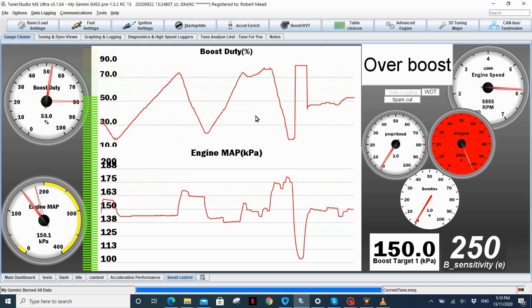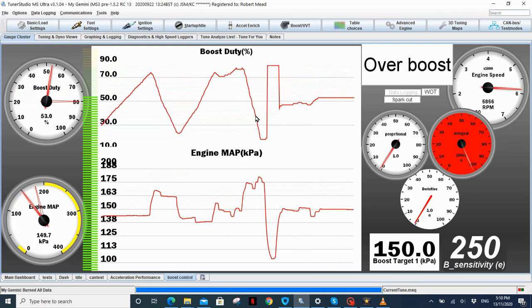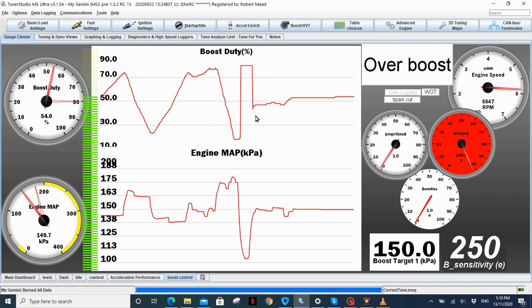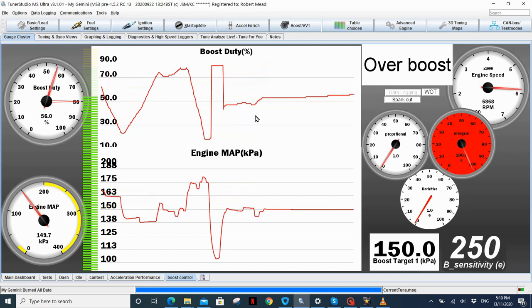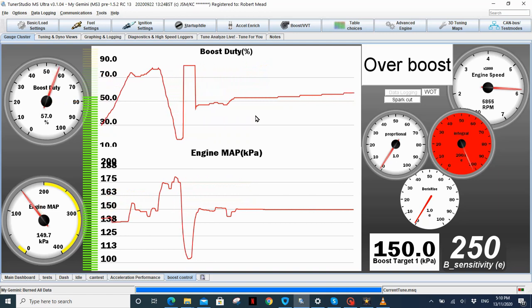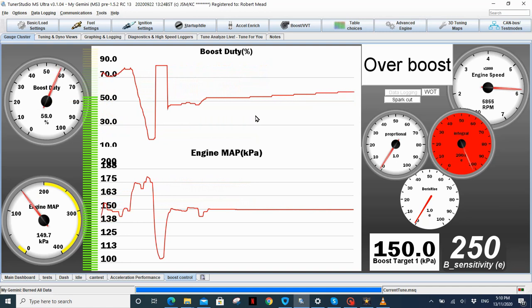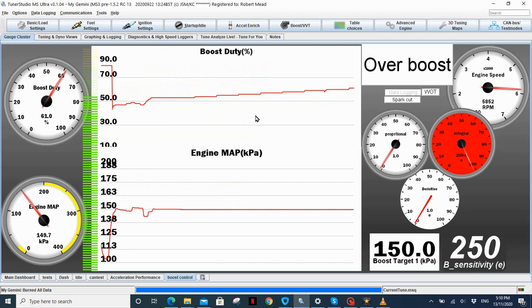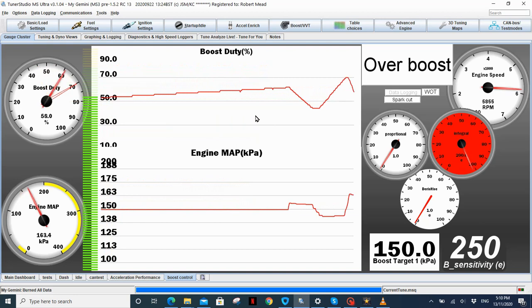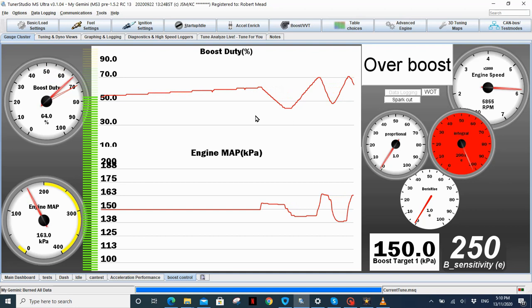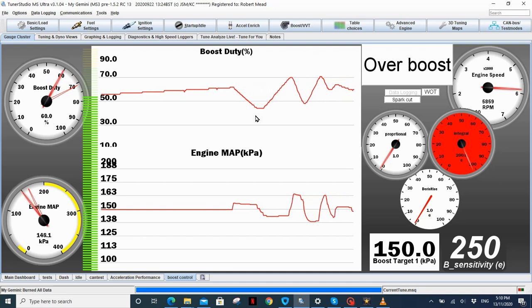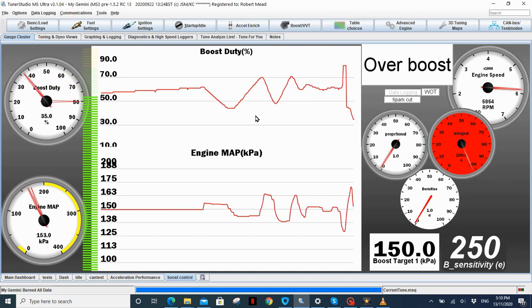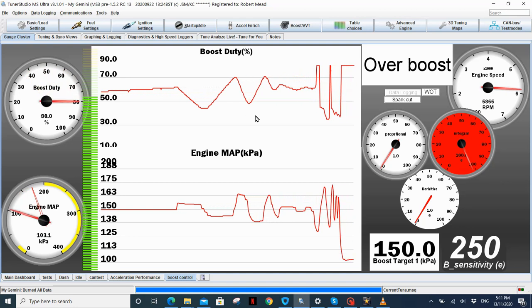I'll just do like, we've got a small error signal there. Yeah, it's kind of hard to maintain, but I'm sitting on 149.7 kPa, holding it pretty steady, which is kind of hard to do. And you just see the integral just doing its little thing there. So that's integral, and that is the most aggressive. I guess it never goes away. If there's an error signal, it's always on the job doing something. So that's the one you probably see doing the work most of the time.